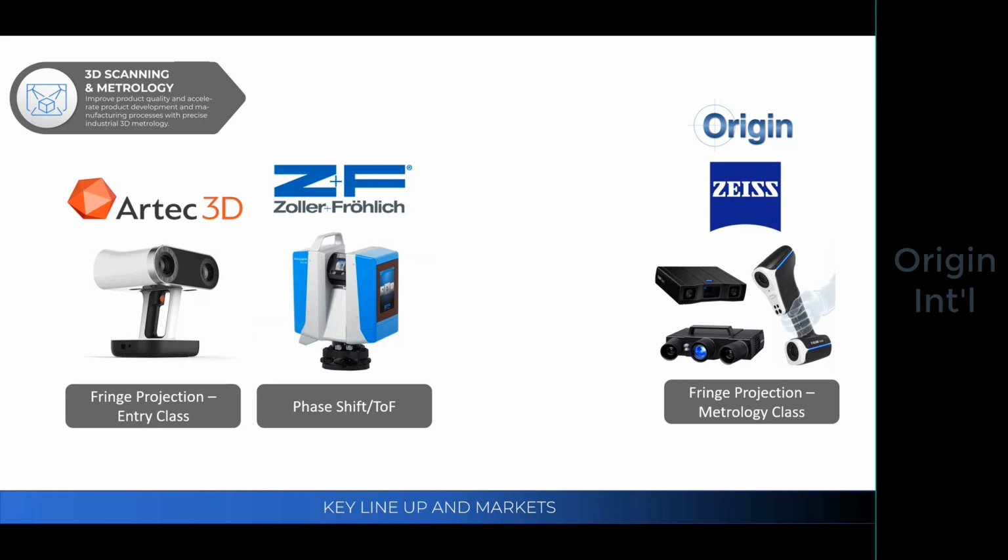So the first little indicator or warning is that while I used scan data to get to some of my conclusions, there is nothing directly correlating that you have to have that. It can come from whether you programmed your CMM with CheckMate, imported your CMM program into CheckMate, or imported your results from your CMM into CheckMate. There are lots of different data entry points. And once you get to what we call the reporting entity level, and that relationship between the two parts, it's not just dependent on scan data.